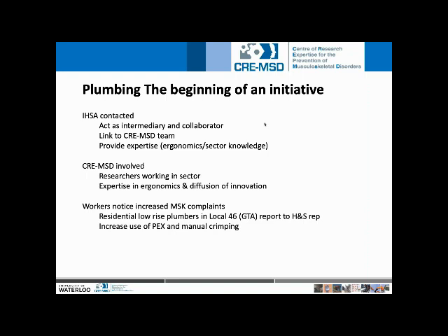Remember, we were talking about tools, and what happened when there was a change in the way plumbing was done in mainly residential low-rise construction, going from using copper pipes for water lines to plastic. We see that there's a change in technology, and of course this change in technology is really related to speed of getting the job done. You could plumb a house a lot quicker with plastic PEX piping because it's flexible. You don't need to have so many joints in the plumbing, and it does change the process.